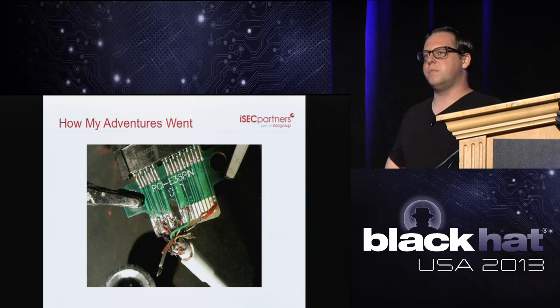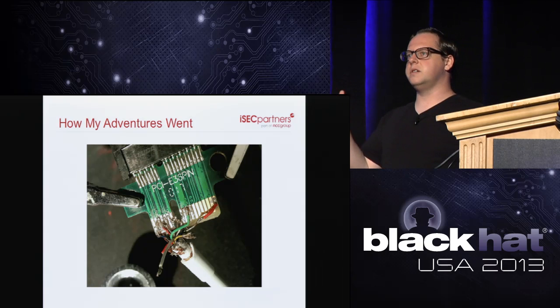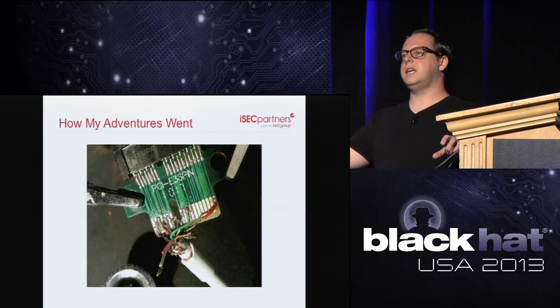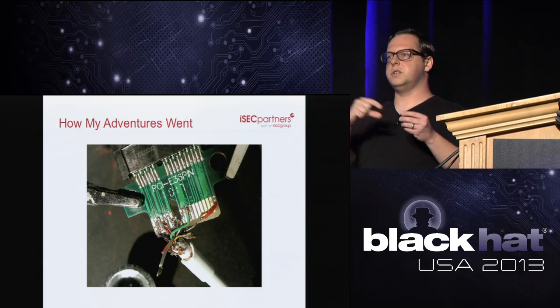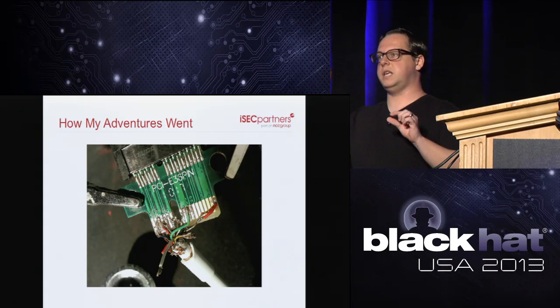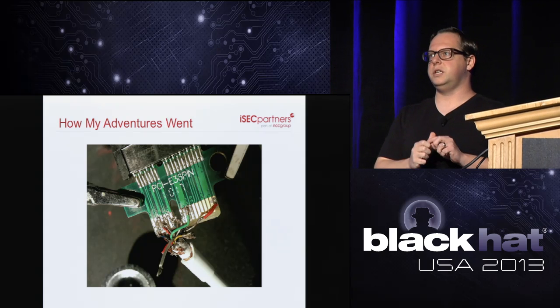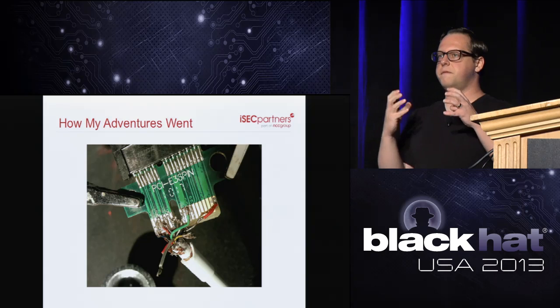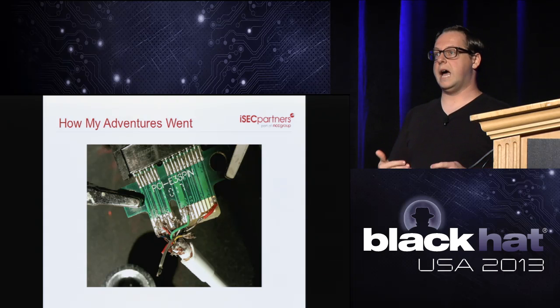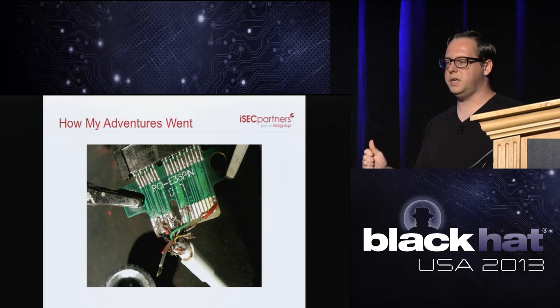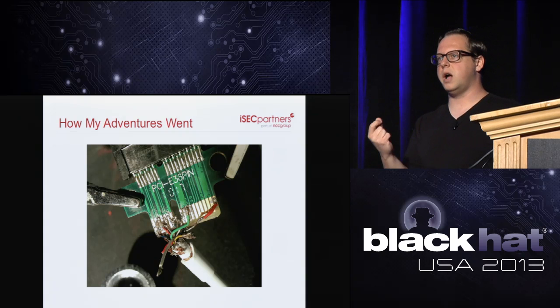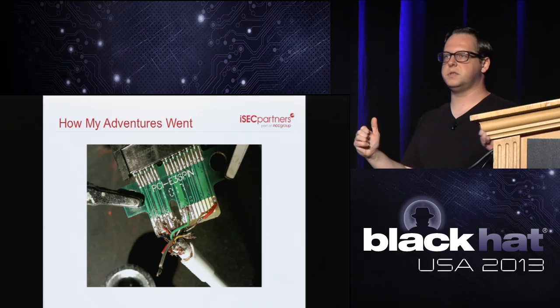These wires are so small. The PCI Express wires that come out, there's a jacket, and then if you pull that jacket off, there's ground wires wrapping around it, and then within there's another wire with a jacket, and then within that, there's the actual PCI Express wire. To strip that first jacket, I used the grooves of a pair of needle nose pliers, and that fit perfectly. It was really difficult to strip these wires, and then getting down to the even smaller wire, I just had to use a really sharp clipping tool and be very careful not to cut those thin wires.